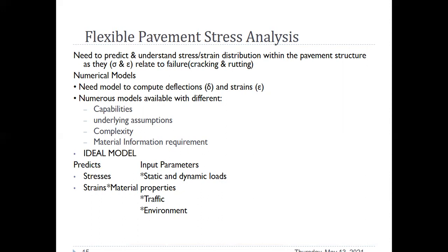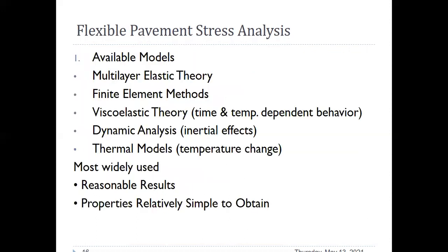In an ideal model, it predicts stresses based on static and dynamic load, and strains based on material properties, traffic, and environment. Different methods have been developed. The famous ones are the multi-layer elastic theory and the finite element method.